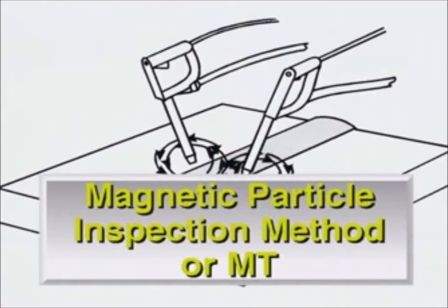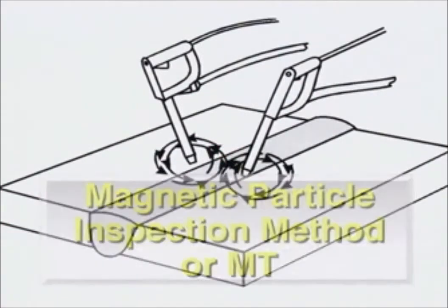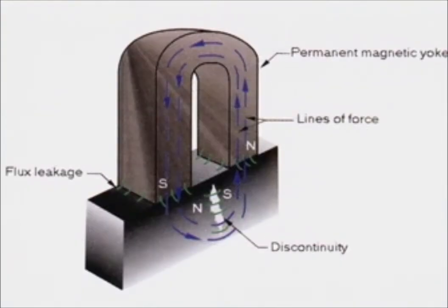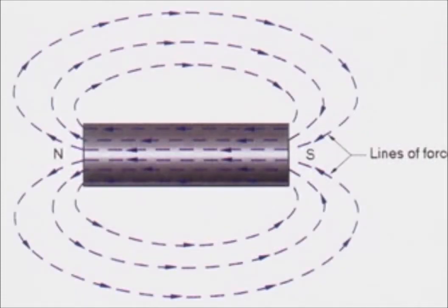Magnetic particle inspection uses fine iron particles in powder form to indicate defects on magnetic materials, such as structural steel. This process works by inducing a magnetic field in a part by passing an electric current through or around it. The iron registers an abrupt change in the resistance in the path of the magnetic field and will be attracted to and outline the crack.